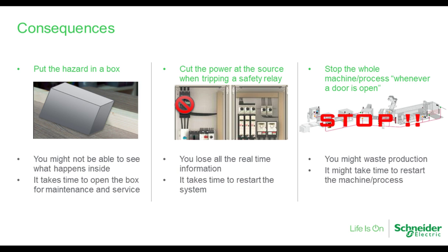Now, you could use a clear cover and then you might still be able to see in, but it's not what we want to do usually. We don't want to totally block people from being able to see or touch the moving parts of the machine, because something needs to be done. So either we're moving materials in and out, there are times where we need to make an adjustment, and if you've got it totally blocked out, that's really hard to do.